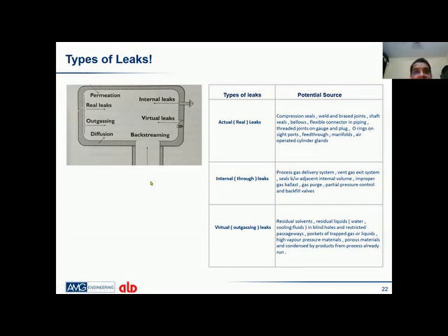Sometimes there is a change because of some minute difference between the closing of the valves and the closing of the application. And since the vacuum pumps are at a very low vacuum level, there can be migration of particles from the vacuum pump to the vessel. Virtual leaks are something like a blind hole, welding leaks, or welding porosity. Internal leaks exist because these vacuum furnaces are connected to different gases, so there can be a gas leak from a gas cylinder or gas chamber into the furnace.